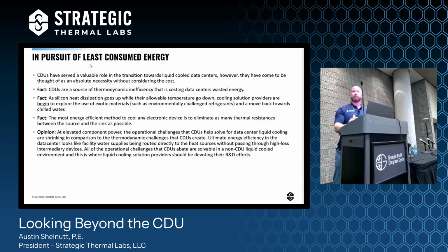That's very true. However, it's not the only way to decrease the convective thermal resistance on a cold plate. Lots of other ways. We, and our competitors, have some other ways. You can make up the difference on surface area through other higher heat transfer coefficient improvement methods. It gets you maybe close to parity with a 50 micron cold plate channel, right? But we just gave you back 7 degrees Celsius, and that winds up being a much bigger net gain in the thermal resistance stack if you start compartmentalizing it that way.